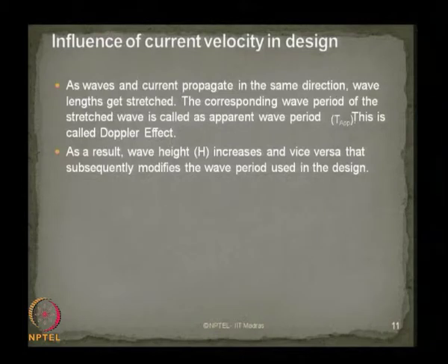So, Doppler's effect is nothing but accounting for stretching of the wave period because of the influence of current on the wave in the direction of propagation. As a result, the wave height increases and vice versa, and that subsequently modifies the wave period which is used in the design calculations.